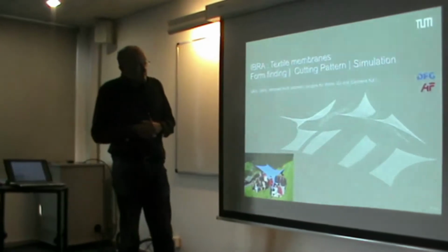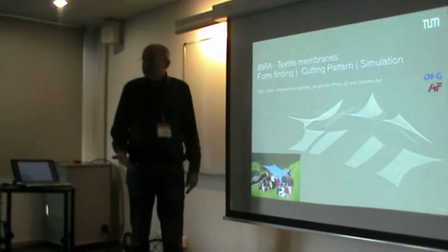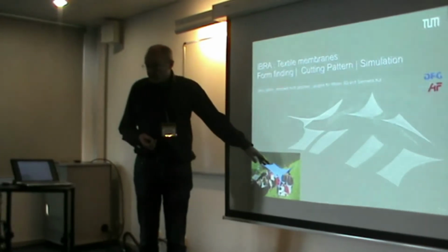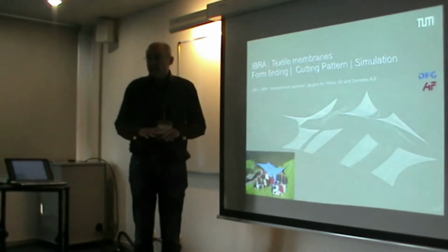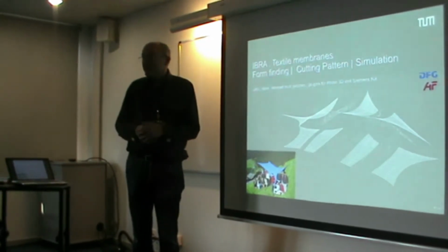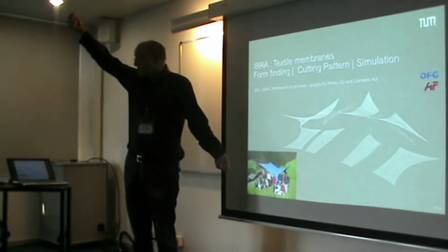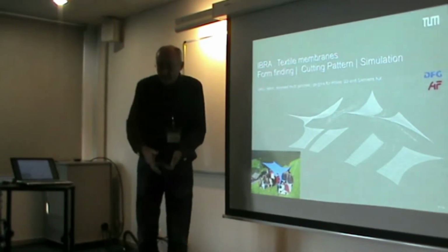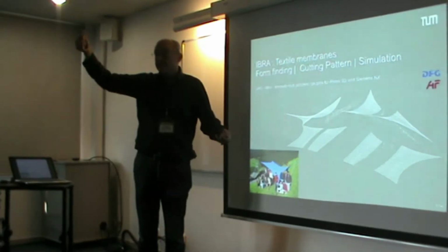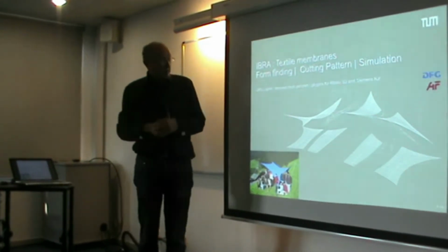What we're doing here is that we formulate everything in a CAD environment, and include the cutting pattern simulation in that. If you like to build that, you typically build it of pieces of textiles, and they have to be cut in the undeformed reference configuration, you would say, as a mathematician. Then you sew them together, or glue them together nowadays, and you put it in space, and by this deformation procedure, from the undeformed into the deformed situation, it will unfold to that surface, which will be in the proper shape with the intended field of deformation.